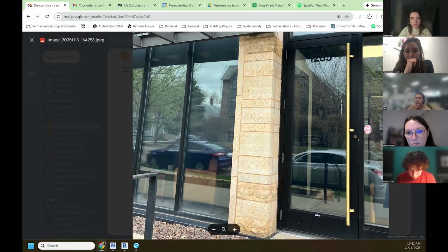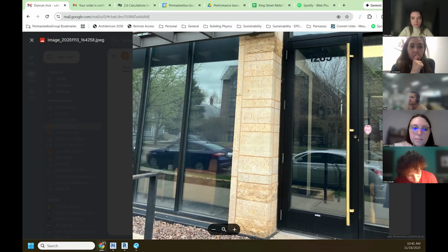I can pick a more traditional example. I just already have these pictures. That's nice because it's a common structure that you see everywhere. When you're using that one, you could modify this facade in the step where you are asked to modify it, by introducing transoms in the middle of the facade, for example. Yeah, that's a good point. Because then you would halve the wind pressure, but you would also halve the dead load, the self-weight of the glass over a small section. Yes. No, that'd be interesting. Thank you.